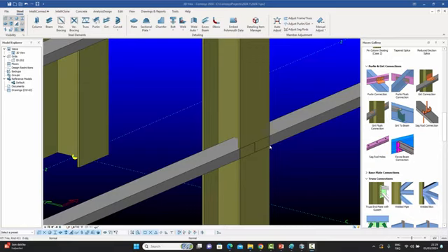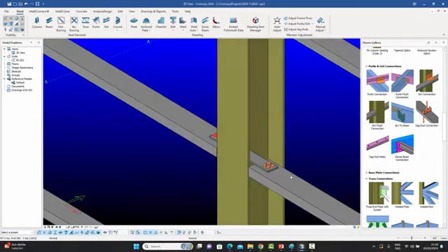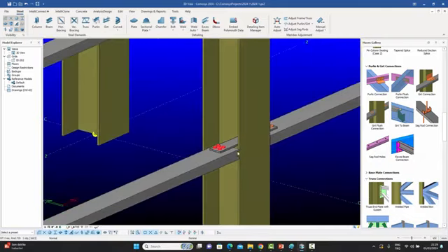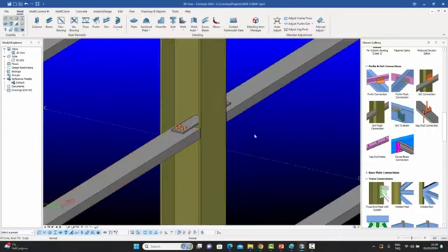So this is a different case, and although it's very easy to do, everybody wants macros to do everything. So our customers requested that we have a flush girt connection, and it's extremely easy to use. You just select the column like the normal girt macro, select girt number 1, girt number 2, and that's it. Your connection is immediate. The girt is pulled back from both sides. The other girt is also pulled back, and your connection is made with a few clicks of the mouse.